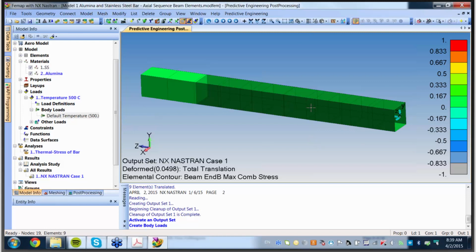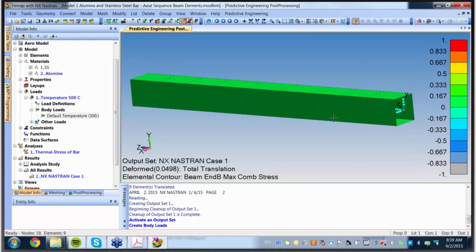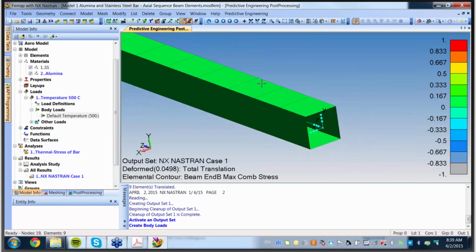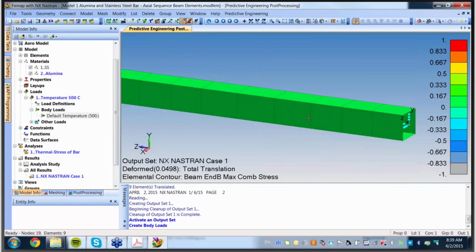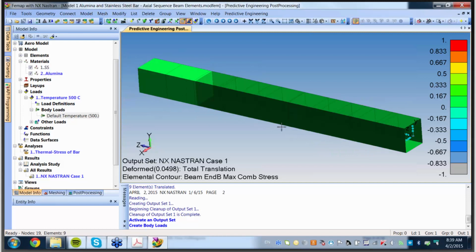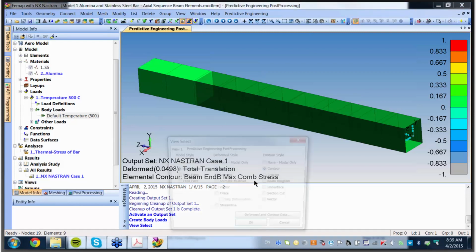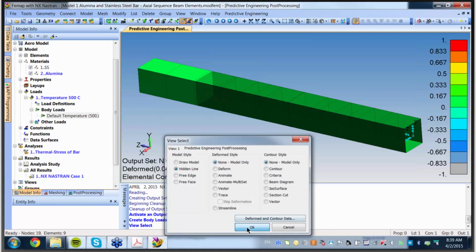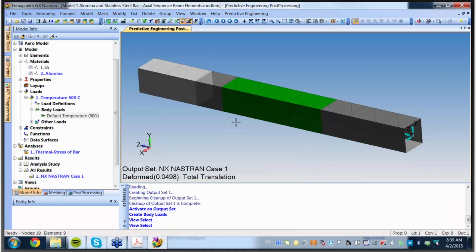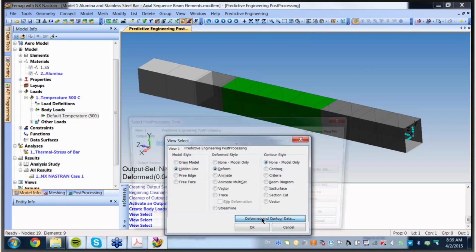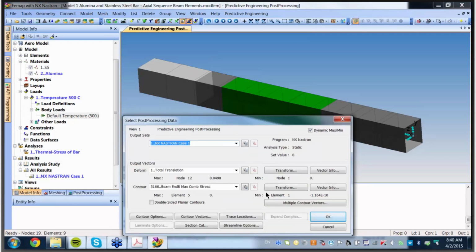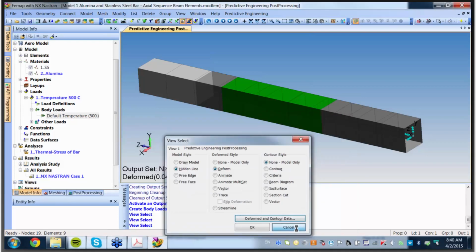You might notice we have our own color scheme and background scheme, and we really don't like the default Femap. Well, it's art; everybody has an opinion about what they like. If you want tips on how to arrange your colors and such, we're happy to dive in. Here you can see the displacement, and if we turn it off, of course it goes back, and turn on the deformed. That's real logical, but you have no stresses. It expands, but you have no stresses because nothing is constrained.